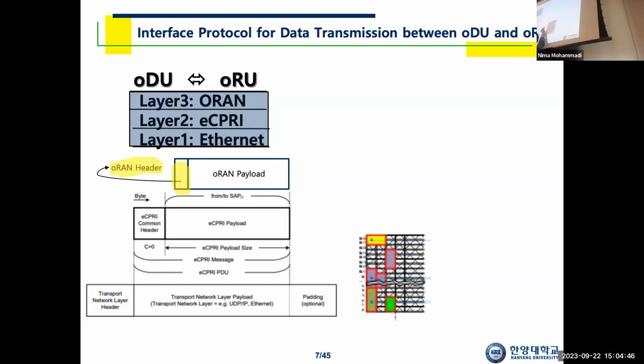Section type 1 is ordinary downlink and uplink. The value, the complex symbol, will be mapped as it is as ORAN payload, okay? And section type 3 is reserved for you to deal with PRACH channel data or the case of mixed numerologies. It's a little complicated, but if I have a chance, then I'll talk about that later. Anyway, you specify section type in the ORAN header.